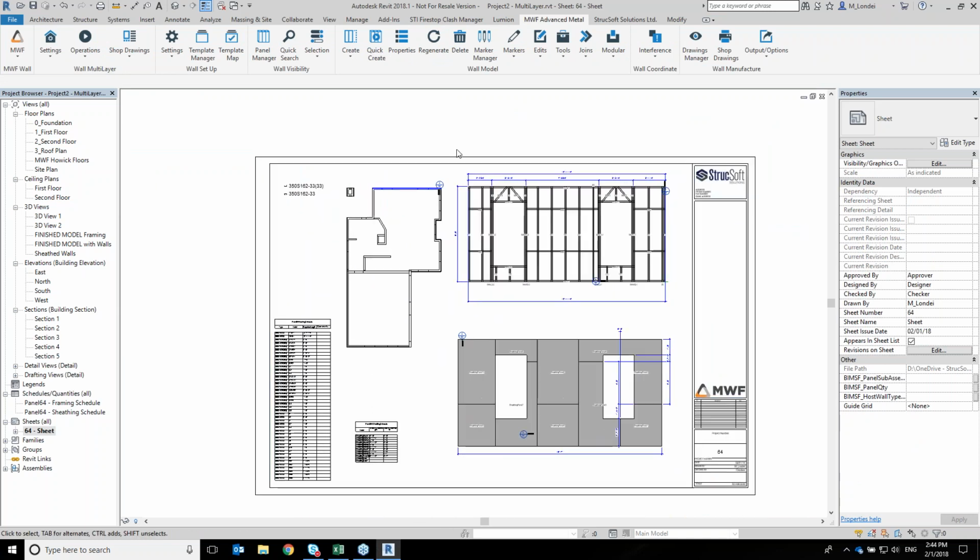Great, thanks, Matthew. I have another one. In the past, drawing templates created in metric would not function, so we would switch to Imperial just for drawing creation. Is this issue resolved? Yeah, definitely. Again, a lot of the issues with metric were stemming from the bill of material. So now that we've actually done away with the static information from that bill of material and are utilizing Revit schedules, you won't experience those troubles with the drawing engine anymore. So metric drawings, Imperial drawings, we're looking at the exact same thing.